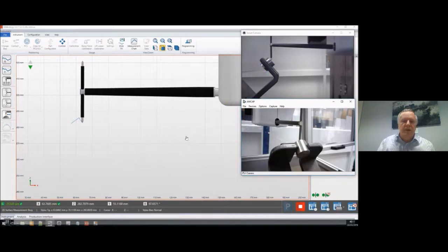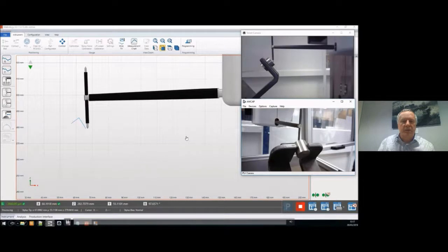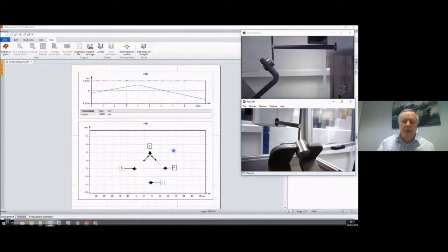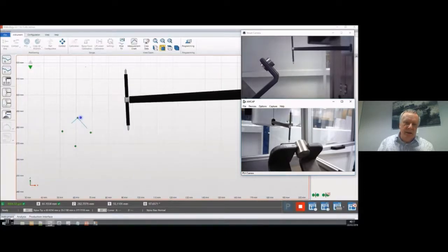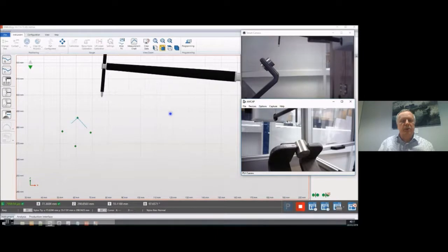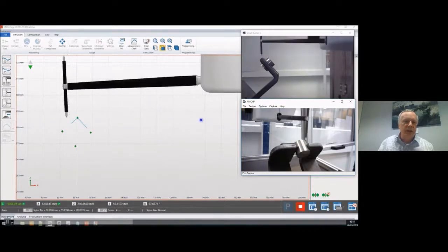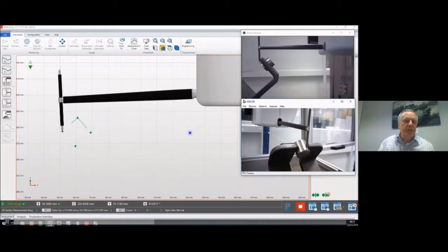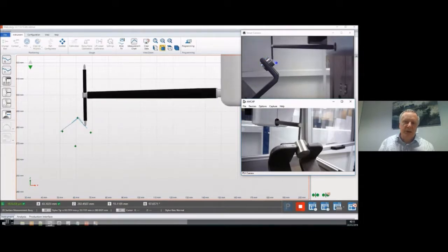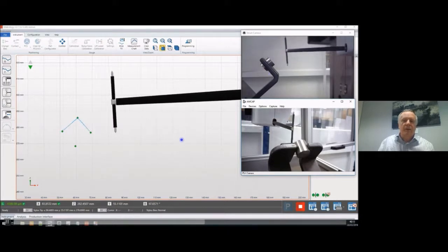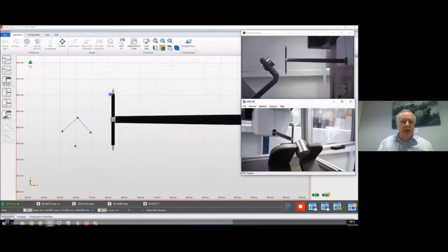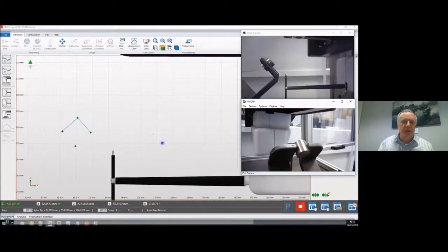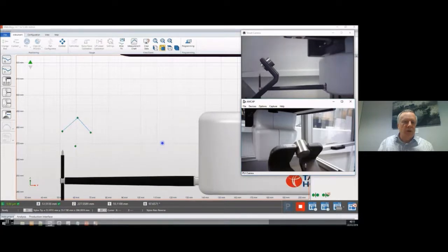If we continue the video here, we will see that we've generated these points from the drawing, A, B, C, and D. These are now available as reference points to do the two measurements. So the stylus moves automatically exactly to the start point, and you can see it on the top right there. We're measuring the first single trace. We now change bias so that we can measure with the other stylus tip, and we're going to measure underneath now. And again, one long trace here.